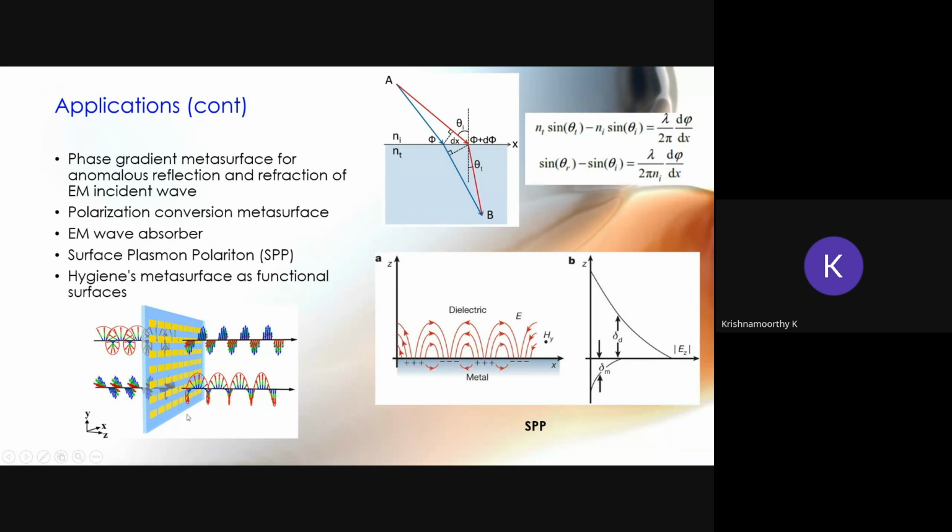Using the metasurface, we can get many applications like polarization conversion, beam steering, beam control and so on. Whenever a linearly polarized wave is incident, either the reflected or transmitted wave we can convert to a circularly polarized wave. If one type of polarization is incident, we can convert the reflected or transmitted wave into another type of polarization. With this kind of application, we can easily use a conventional simple antenna to produce circularly polarized radiation, the antenna applications.